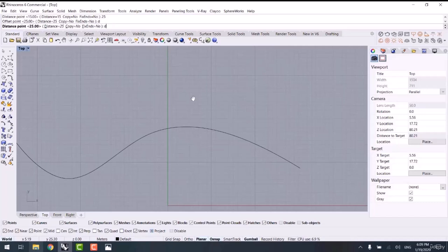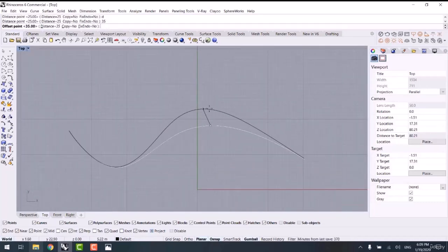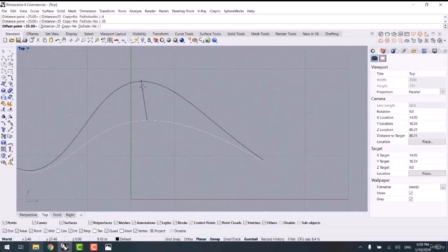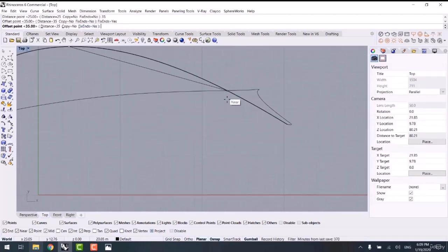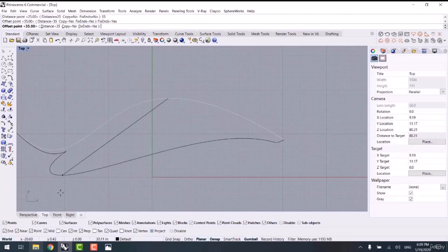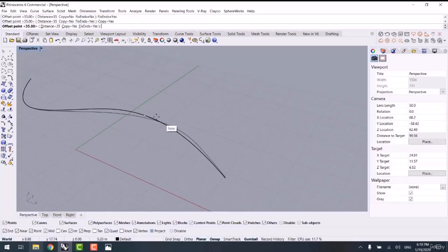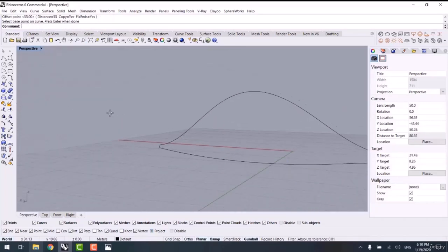This way. And here we can even click on the curve to set the distance instead of entering the value. So this way you can control the distance, and here as you can see I have specified 35, since it has been increased to 35 units on the curve. Here we can set fix end to yes, so then the end of the curve will not be allowed to move. And also we can set copy to yes in the options of the command line, and holding down the control button, model such a curve.